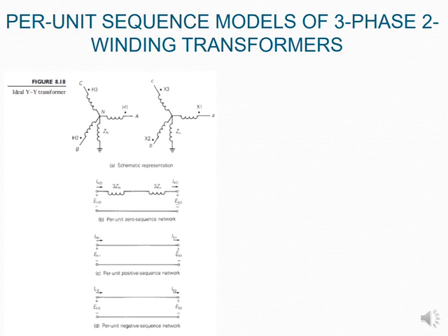In your schematic for your zero phase sequence, we know that we're going to have the 3 times the Zn, and that is the one that's going through to ground, and then we're going to have the smaller Zn, which is really looking at your 3 phases that you have in the system. Then you go to your positive phase sequence, and you can see that that one would really only be looking at whatever is happening on one of your phases.